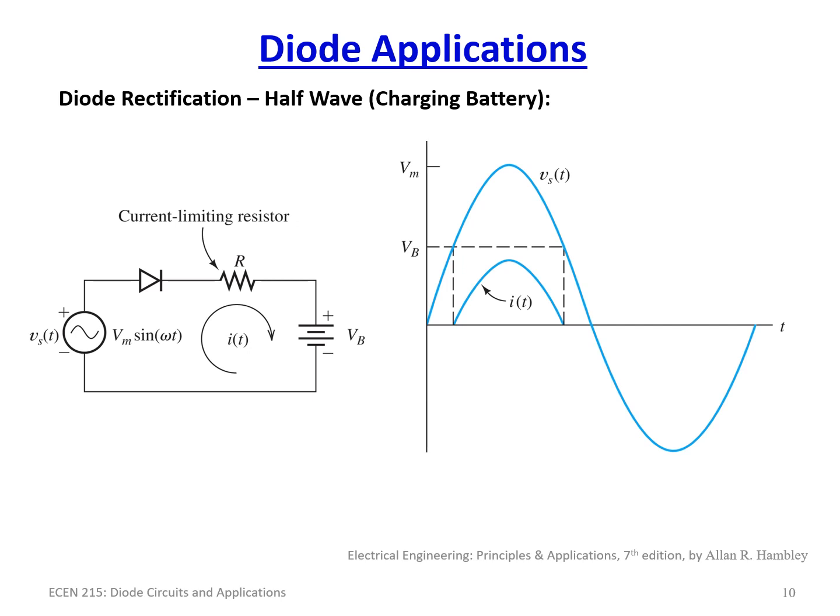In fact, a lot of old equipment developed in the 1970s and 1980s, if they had nickel-cadmium batteries installed, would simply use a diode and a resistor, and you would have basically a little wall wart, a little plug you would plug in the wall, and instead of being DC, it would just be a transformer, for instance 12 volts AC, coming in here. Then of course you'd have a diode and resistor, and every cycle you would get a little spike of current, and it would allow it to charge the battery little by little. This is actually very common.